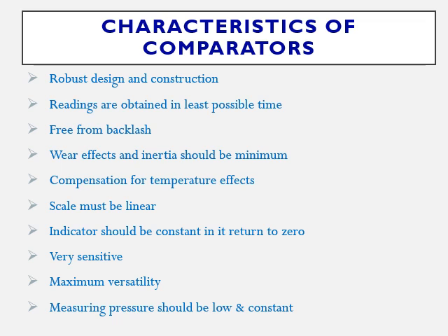The scale should be linear as much as possible, so that the operator can understand the readings easily. The indicator should be constant in its return: once the component is unloaded, it should return back to the zero reading, that is, without any kind of hysteresis loss.